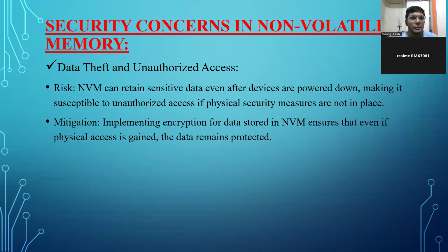Security concerns in non-volatile memory: data theft and unauthorized access. As NVM is not power supply dependent, even after power loss it can store data. So it might sometimes store very sensitive data after power loss, which makes it susceptible to unauthorized access if physical security measures are not in place. Mitigation: implementing encryption for data stored in NVM ensures that even if physical access is gained, the data remains protected.